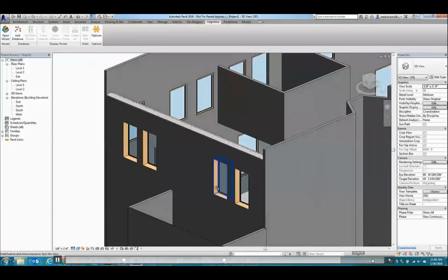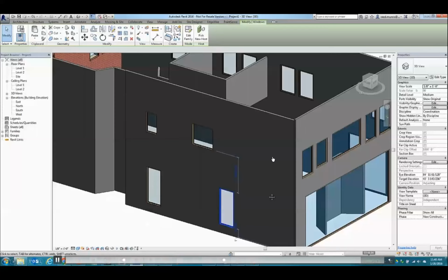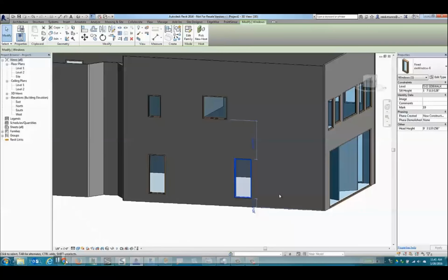And it is really, really quite satisfying as a result. So this is really the interesting part, is that we do not spend a lot of time anymore trying to generate a 3D model from point cloud. We can use Edgewise to help us extract as much as possible from the point cloud data. Then we just come back to Revit here with almost 75 or 80% of the 3D model already generated. And we can just complete the rest quite easily in Revit. It's really a lot of time gain compared to what we can do on the regular or classic laser scan workflow.